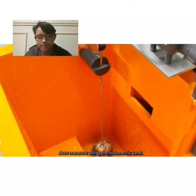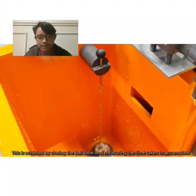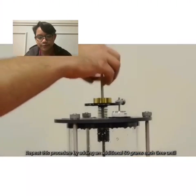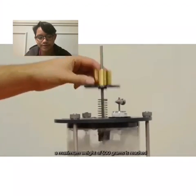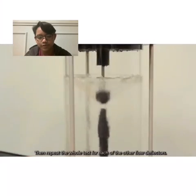Now measure using the volumetric tank. This is achieved by closing the ball valve and measuring the time taken to accumulate a known volume of fluid in the tank as measured from the sight glass. Repeat the procedure by adding an additional 50 grams each time until a maximum weight of 500 grams is reached. Then repeat the whole test for each of the other flow deflectors.